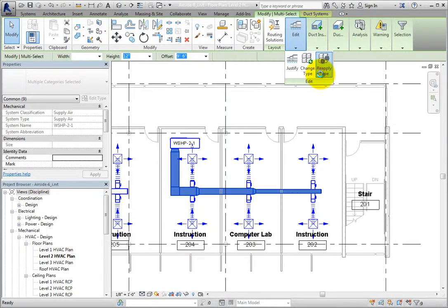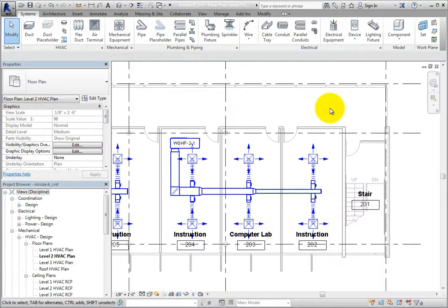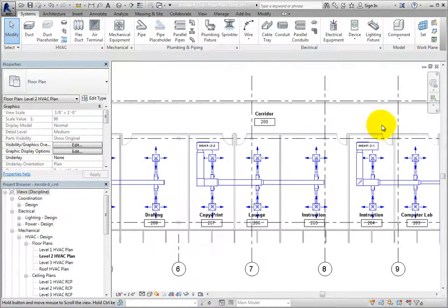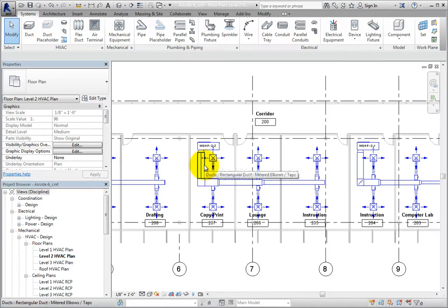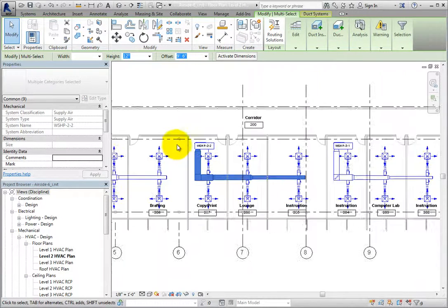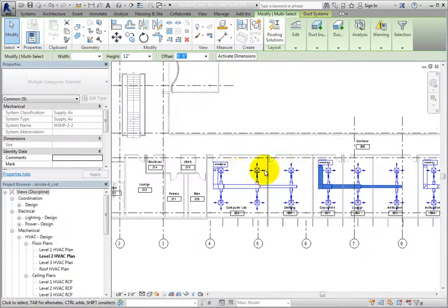Once you do, Revit updates the duct type and the elbow changes to match the elbow we just loaded with turning vanes. You can quickly update the other 2 systems as well. Hover your cursor over one of the main ducts on another system, press Tab to highlight the chain, and then click to select the ducts. Then move your cursor over a main duct on the other system, press Tab to highlight the chain, press Ctrl, and then click to add the highlighted ducts to the selection set.